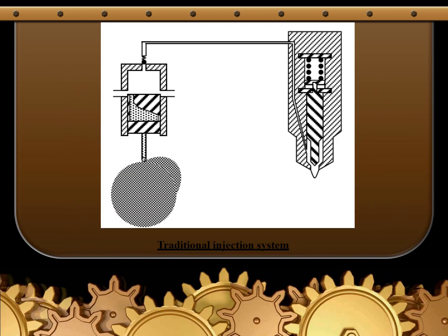This is the helical groove. This is a conventional system. Fuel is the first point. There is the helical groove. The dotted line is also given. The fuel supply goes along this line. In case the plunger moves up, the fuel comes in this way. With the help of the plunger, it moves that side. But in the CRDI, the fuel is given directly to the nozzle.